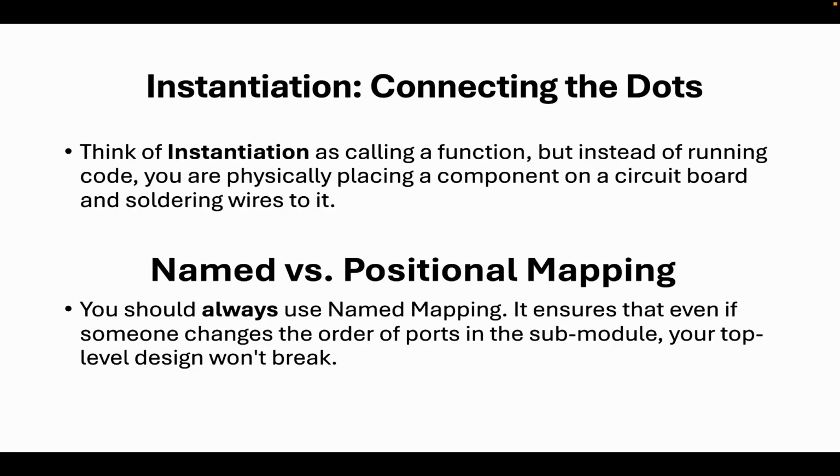Instantiation. Instantiation is very important because if you have multiple codes running, if you want to bring a smaller block into a larger code, consider you are doing a 4-bit full adder and you want a 1-bit full adder to be instantiated in the 4-bit full adder. At that time, instantiation becomes very important. Let us see the difference.